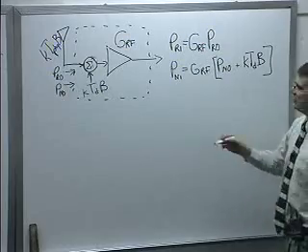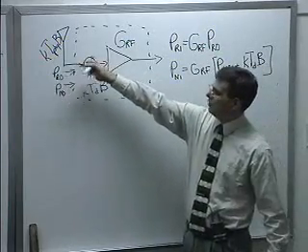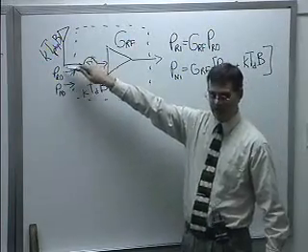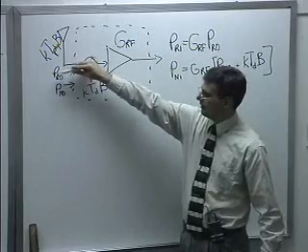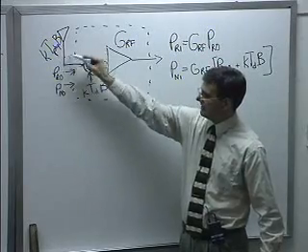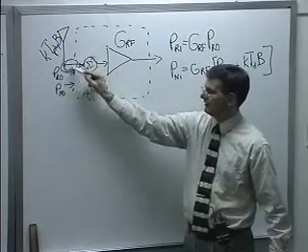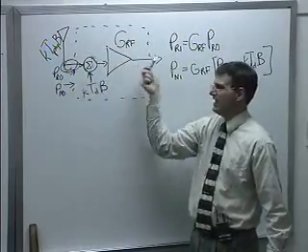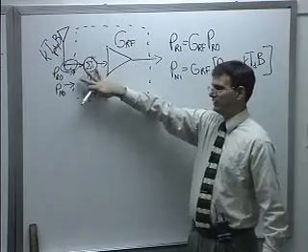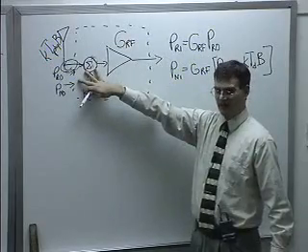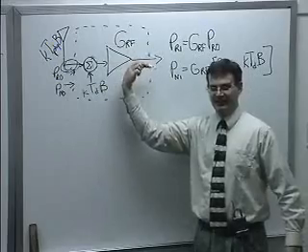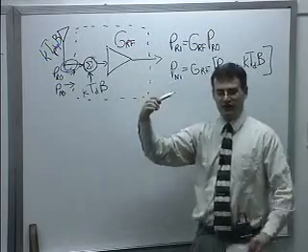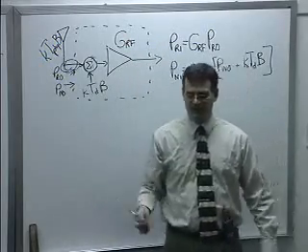And so notice that the carrier to noise ratio will never get any better than it does at this point, because this is always going to have the same carrier to noise ratio through the amplifier, excluding any device noise that you add to it. And then you're going to add the device noise, so it's always going to degrade your carrier to noise ratio. Amplifiers are kind of like a rising tide.